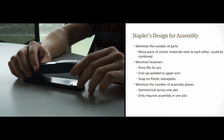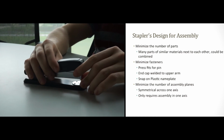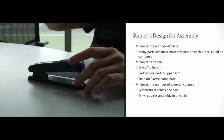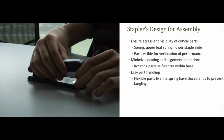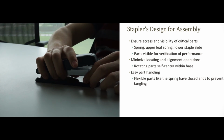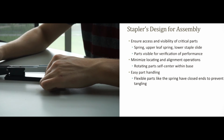With regards to the actual actions of assembly, the design of the stapler minimizes the number of assembly planes. Once the initial parts have been assembled via machine, the final assembly requires only one access and can be assembled in the z-axis. The design also ensures visibility of all critical components. The spring, upper leaf spring, and lower staple slide are all easily visible and vital for optimal performance of the stapler. The parts utilized in the assembly of the stapler are also self-locating and aligning.